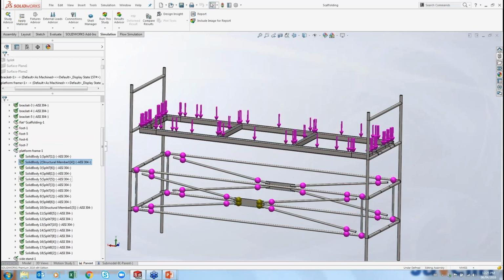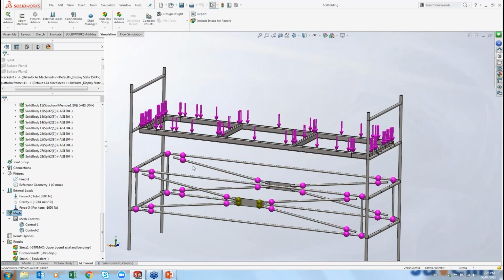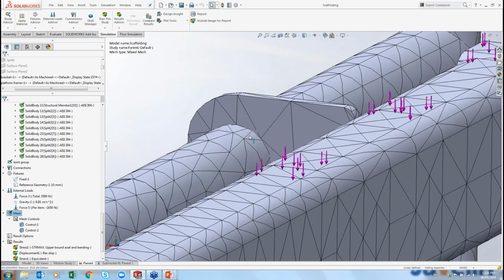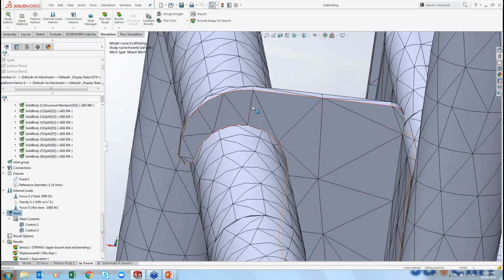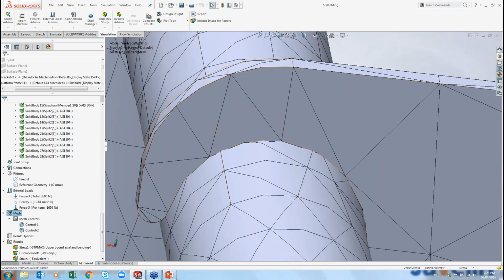Now, with this, it's a very, very coarse mesh, and I'll show you guys what the mesh actually looks like. So I'm going to look at one of the hangers in detail here. That's not a refined enough mesh to give us even a close to accurate stress in here. In this case, we only have one element going through the thickness. We would need a minimum of sort of 4 or 5 in there. I'd like to have a lot of element density right around the contact area, so I can see basically good resolution of how deep those contact stresses go.